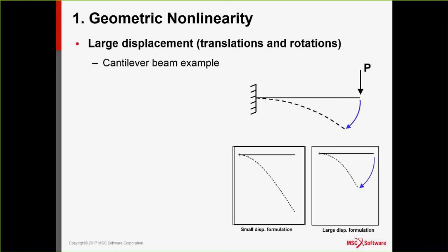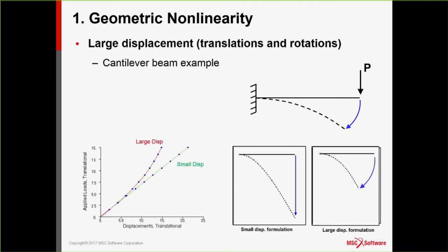Now, on the right-hand side, we're going to turn on large displacement, or the geometric nonlinear capability. And now we're going to actually track the deformation step by step, incrementally solve it. And now you can see the deformation is a lot more reasonable, right? It needs to bend. And actually, when it bends more, at some point, if you look at the free body diagram, the beam will start to react tensile load inside the beam in order to react the vertical applied load.